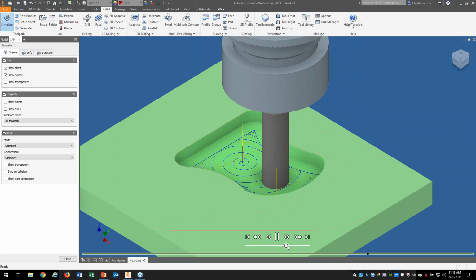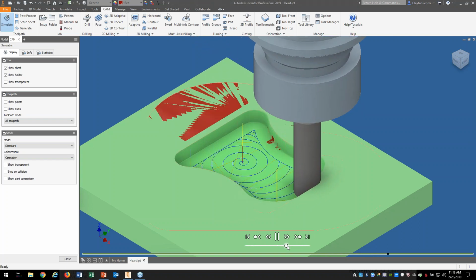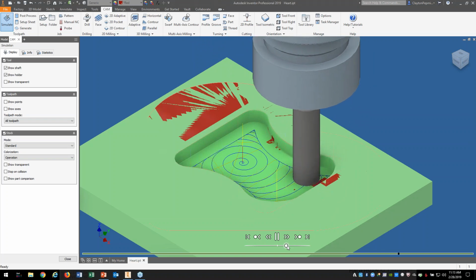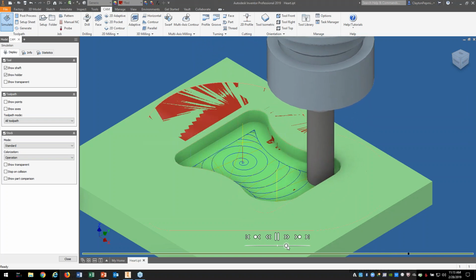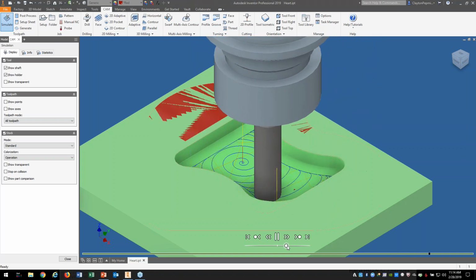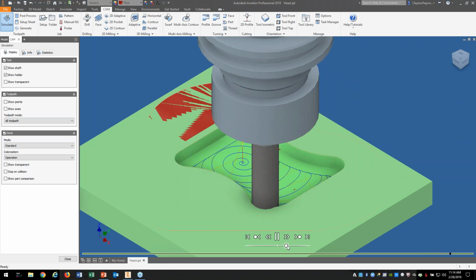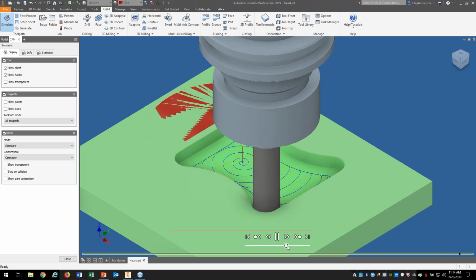Again, you might notice what it does when it hits the end wall down here. When it makes contact, it starts following the end wall. Then all that's left is obviously the corners. It's taking stabs at it. At no point in time during this entire pocket did it bury the full width of the tool.